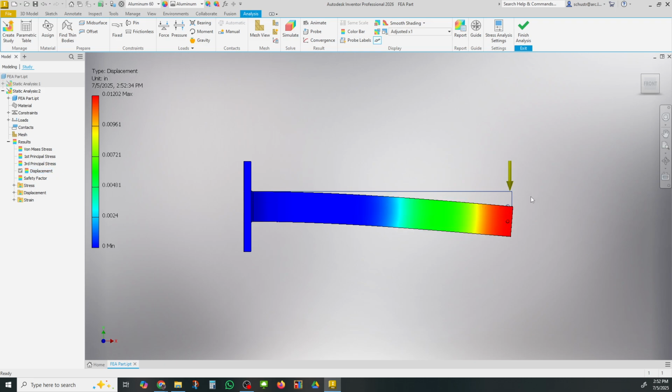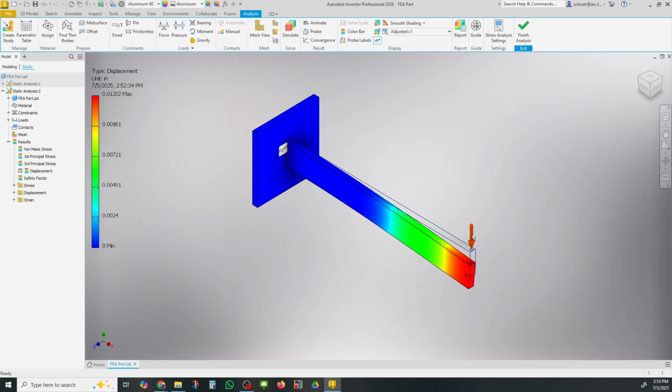In the displacement, it just wants to show you what the shape is. It's going to bend only 0.012 inches. Okay, about very, very small amount, less than about 1/100th of an inch. Okay, so I can do all that, and then if I want to change this force and see what it does in the other way, I can take pictures and I can do all sorts of stuff here, but I can remember that this is 0.012.